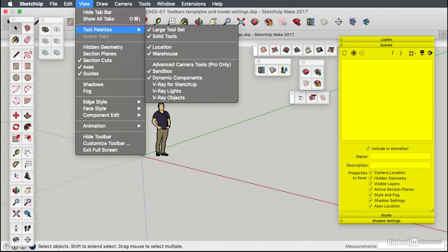And for these, they're under the window menu as before. So that's pretty much the setup. You can configure this toolbar on the Mac, right click on it, and then choose Customize Toolbar. It'll give you a big window of all the potential icons that you can then just drag up. So you might just want one from a cluster, and you can drag that up and dock it into this. So that'll get us set up. Then we can look at how to move around the model in the next video.